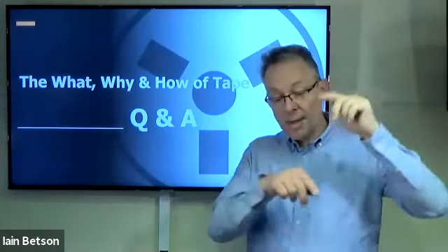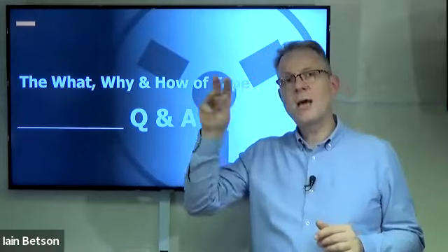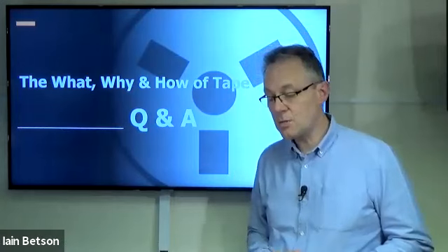And of course your machine, where the erase heads are only designed to take those two furrows out, will not be able to get rid of that fringe material that your record head, or your replay head I should say, might be picking up. So the only true way to fully wipe your tape is to put it through a demagger and blast everything off, making it a completely wiped tape.